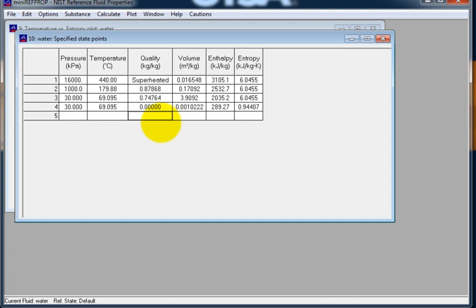All right, it goes through the pump. This is something different than your hand calculations. In the software, you can handle constant S through the pump. What comes out of the pump, state 5, it's 16 megapascal, isn't it? But I don't have to do V times dP. Hand calculations, that's the way you do it. But here, just grab that S, copy, put it down here, paste.